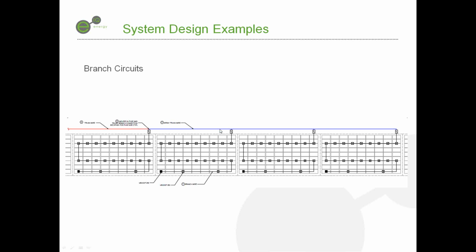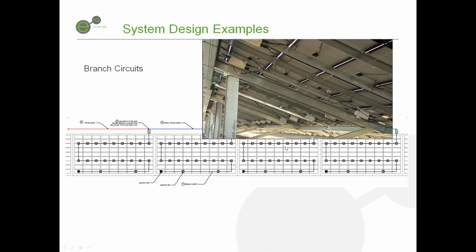But the other important thing to note is that each one of these is exactly the same structure. So as they fed into that trunk line, really all the electricians had to do was recreate that same wiring diagram block after block after block throughout the entire array. You've got an idea of what that looked like from earlier, where we have the vBoost running up and running down, and the module is simply connecting into each one the same over and over again.